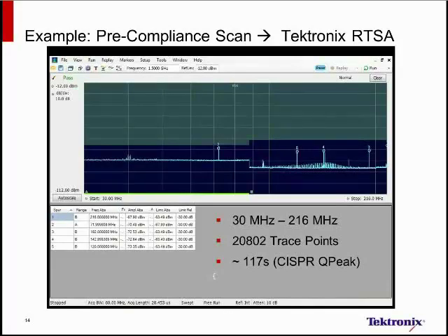And we did the integration, and we found that we only actually had 5 carriers identified, and with quasi-peak detection, none of these 5 were above the limit. They were all below the limit. But because I specified my threshold to be within 10 dB of the absolute limit, it still identified them as could be a problem for me. With this information, I could go back into my design and find out specifically where these frequencies are being used, and if necessary, take corrective action.